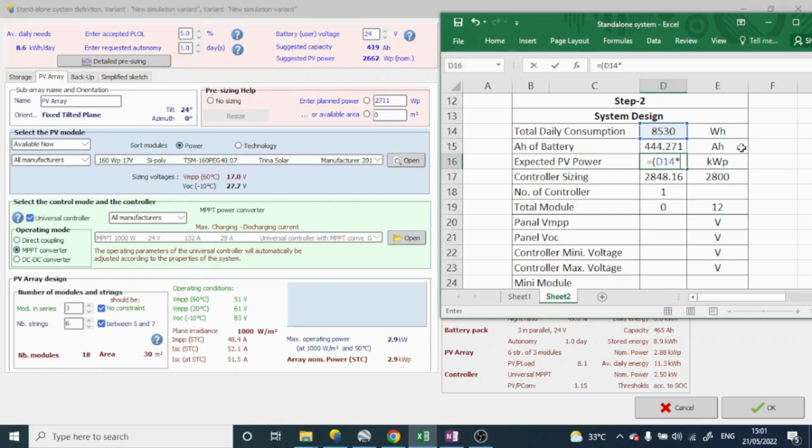That is why we are taking the overload factor as 1.3 here. We take it like this and close the bracket. So this is the daily consumption as per the current requirement with overload factor, and this is going to be divided by 4000, because as per the thumb rule, 1 kilowatt of a solar system generates 4 units on an average daily basis.